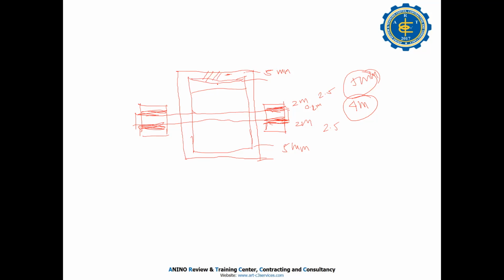If you did not change it, your impeller or the blade of your pump touches the casing, then it is damaged. That's the reality, and that's why you change the bearing. You get what happened. So that's why if you have looseness with your bearing, then you must change it. Another input to you, maybe the time will come.